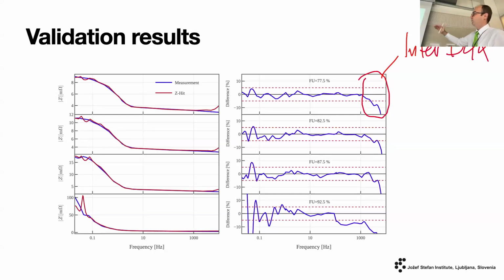But as we increase the fuel utilization, we actually move our set point towards one of the edges of the IV curve. What we were doing is measuring here, and when we were changing fuel utilization, this set point slowly drifted here. To be more precise, this knee started to move this way. So our set point became part of the nonlinear region.